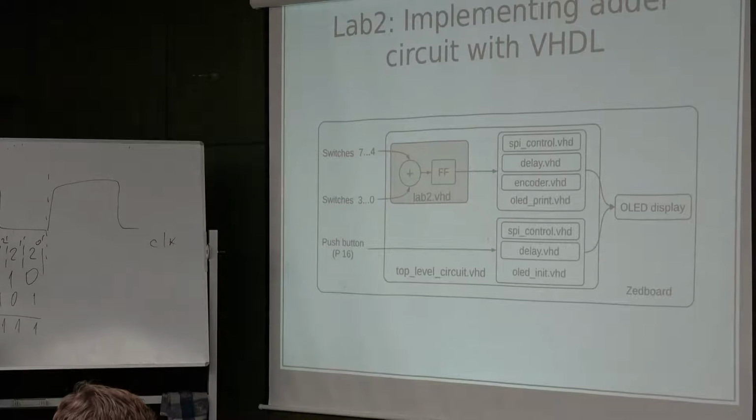So what we call synthesis is converting VHDL code to RTL level and then to lookup table level. But the way we really physically place it on the chip, so which particular lookup table will be used for what, and how we route wires between those logic blocks, this is what we call routing. Because when you see a report, you might see something like synthesis is done, routing, implementation. So this is what stands behind this. Yeah, any questions at this stage? But I think you should be ready to start, so you have everything you need.